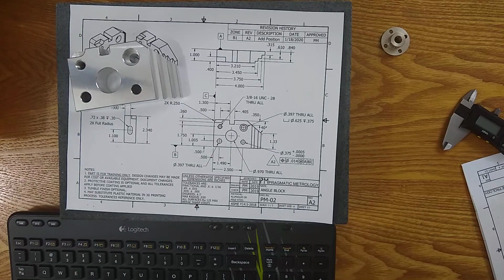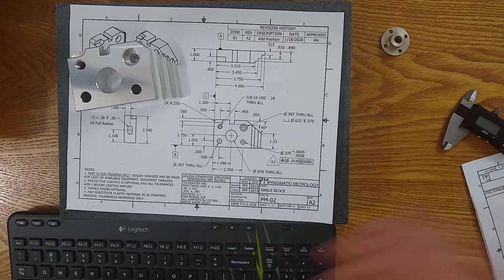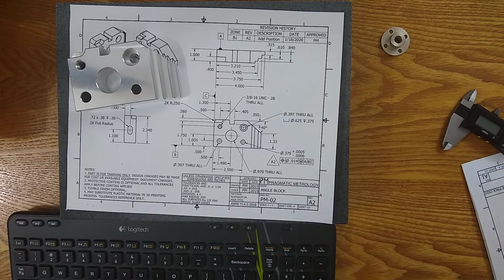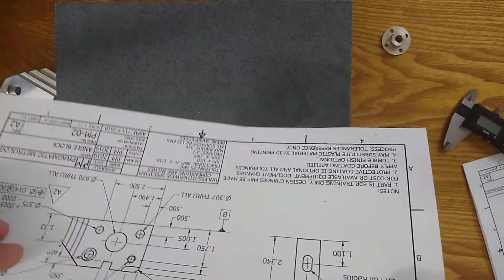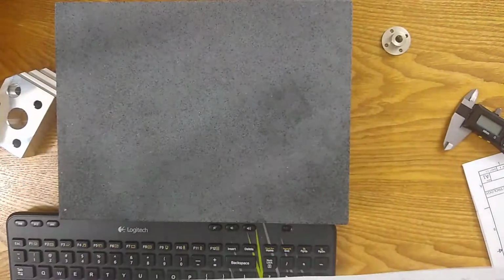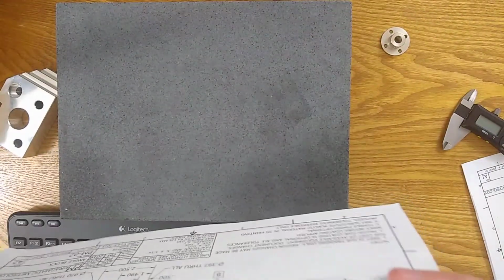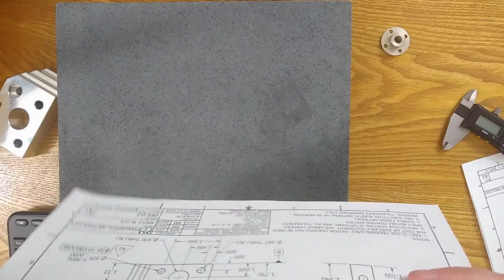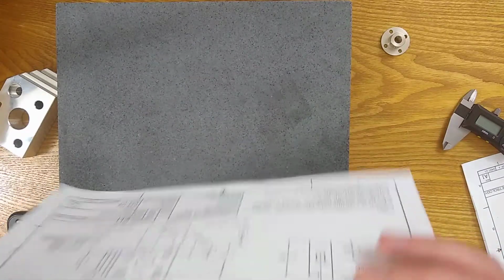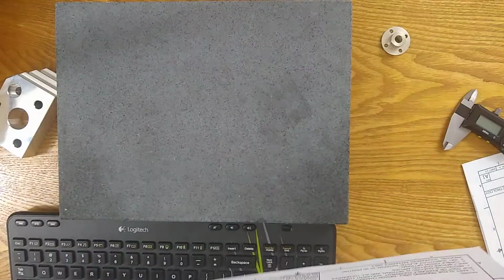Undefined datums are something that's implied sometimes, but not stated. I created this print and defined the 3 datums. Sometimes prints don't define the datums, right? I did, but as I mentioned, a designer and engineer can do anything. So it may not have defined datums, or it may have multiple datums.